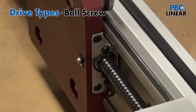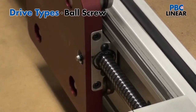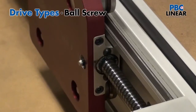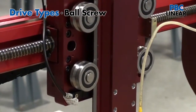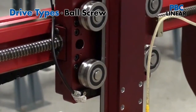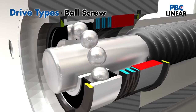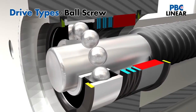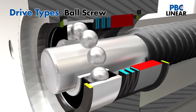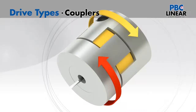Both lead screws and ball screws offer excellent repeatable performance, with ball screws having the advantage where lower friction and higher efficiencies are needed. Most often they are favored in machine tool applications or where large loads are a factor. Be aware that journal bearings and the retainers used for mounting a lead screw, ball screw, or the pulleys for a belt drive are further components that can introduce play or backlash into a system.